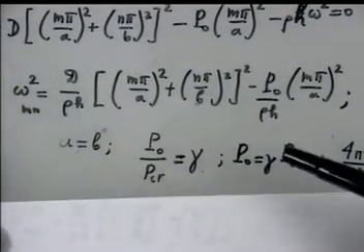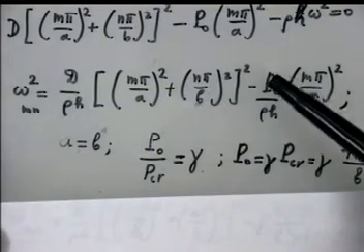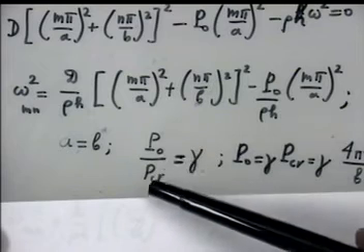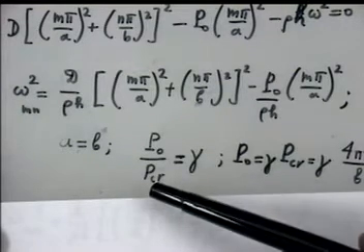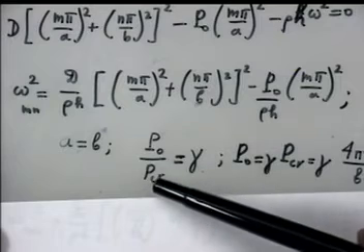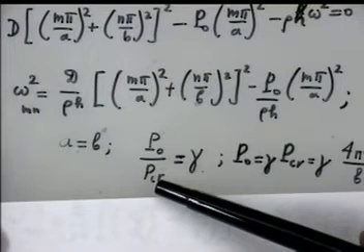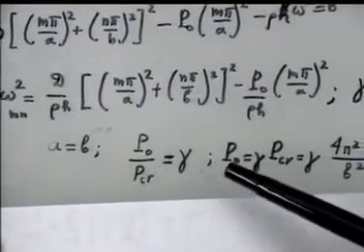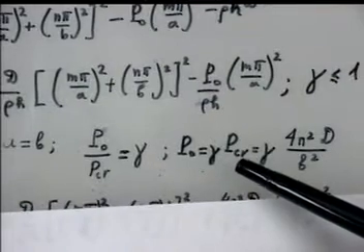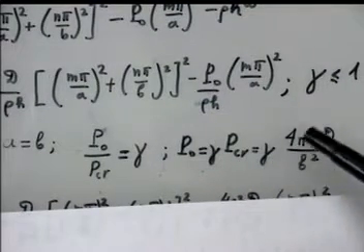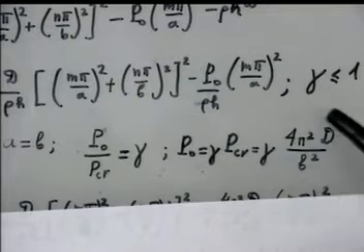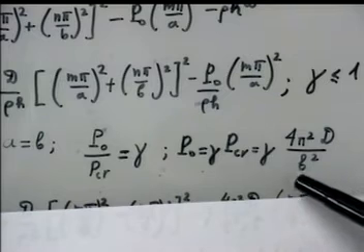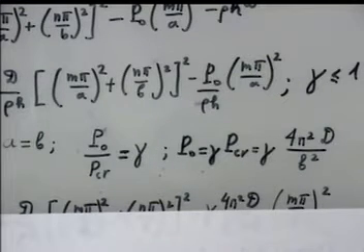Now I just put as follows. Look, please. There is this P0. P0 can be related as a fraction of critical load. P0 is gamma times P critical. So P0 equals gamma times P critical, and it equals gamma times, for the square plate, we found this expression, 4 pi squared D over b squared. We already found it previous time.